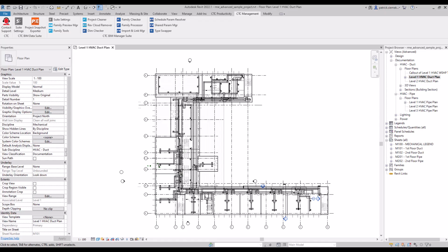You have probably run into a scenario within your Revit projects when it comes down to purging out or cleaning up your projects. Let it be if you're archiving a model, sending out the model to another consultant, or just cleaning up your project as you are working through it. There are a couple of different ways you would approach this with Revit out of the box: utilizing the Purge Unused tool, or just doing some kind of manual browser organization and removing things as needed.